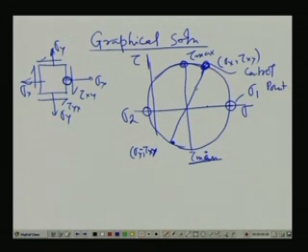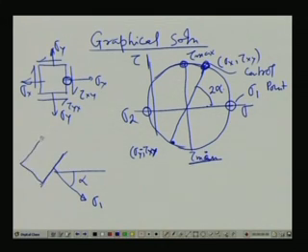Now, from the control point, how are we reaching this point? By 2 alpha. So, we draw a line, come here by alpha, just make it half. Then this gives the orientation of sigma 1 as well as the value of sigma 1, you can read it from here.